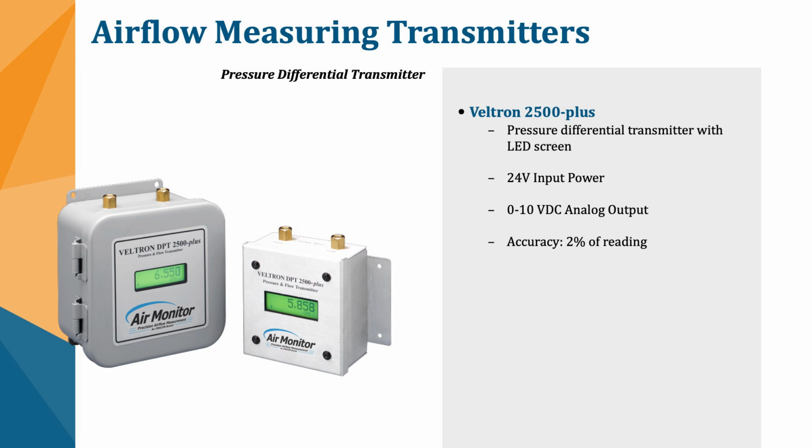Now, the other options we have are from a company called Air Monitor, and those are all units that we have to sell with the damper attached. So these are great transducers. They are a bit costly, but do have about the same inputs and outputs. They do have that screen, so you can look at the damper and get a CFM reading out of it, but they don't have that connectivity that some of the thermal dispersion units use, like BACnet connectivity or a Bluetooth reading to a phone.